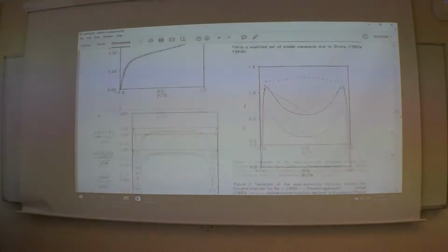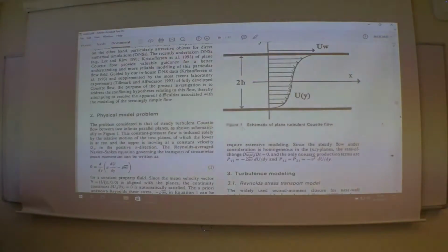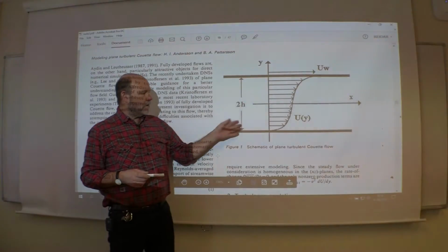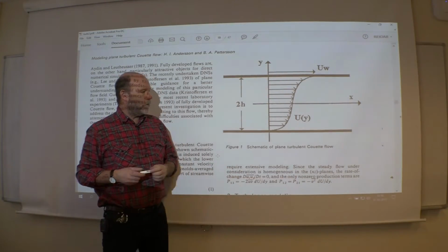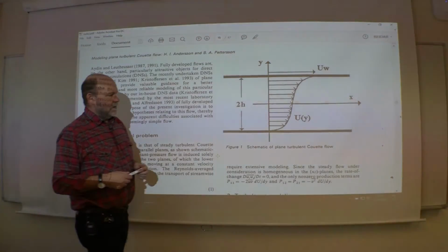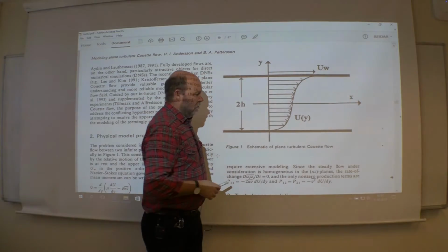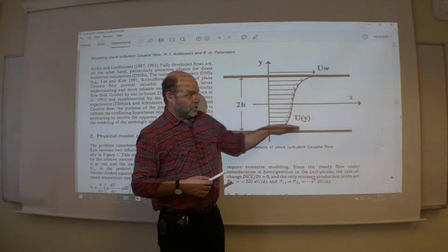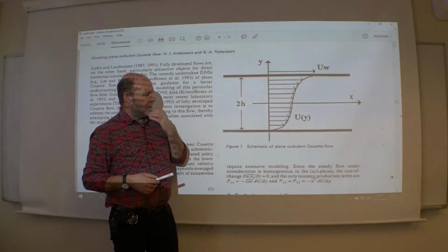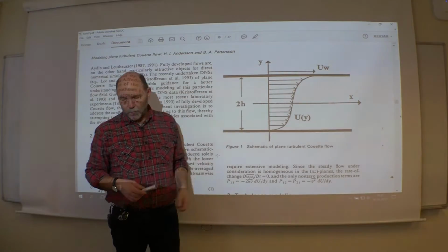And for this flow, although very simple geometrically, you clearly have an inhomogeneous type of turbulent distribution. It's much more turbulent activity close to the walls. You have some turbulent structures alongside in the streamwise direction. Totally different when you go in the opposite direction or between wall to wall.